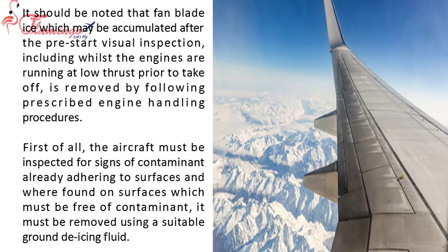It should be noted that fan blade ice, which may be accumulated after the pre-start visual inspection, including whilst the engines are running at low thrust prior to takeoff, is removed by following prescribed engine handling procedures. First of all, the aircraft must be inspected for signs of contaminant already adhering to surfaces, and where found on surfaces which must be free of contaminant, it must be removed using a suitable ground icing fluid.